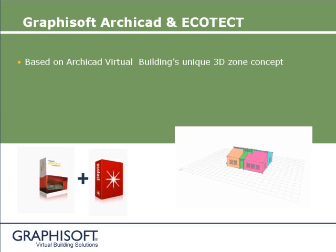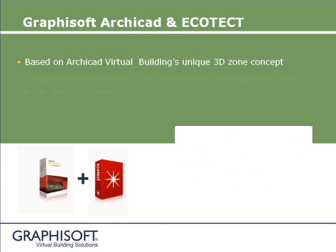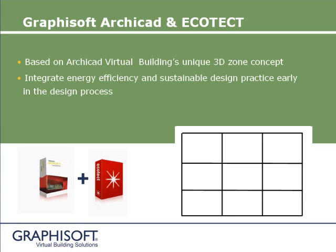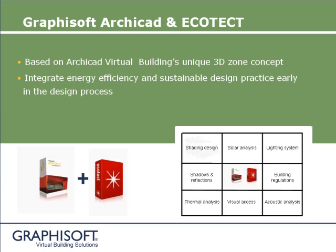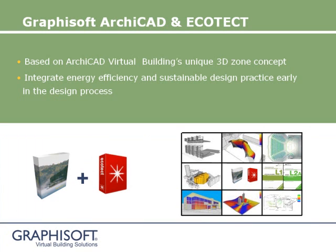ArchiCAD zones, 3D volumes, are the cornerstone of analysis. Together with Ecotect, you can run a comprehensive set of building performance analyses, covering thermal, ventilation, light, acoustics, and more. Designers can get a wealth of information as soon as their ideas are formed into a rough mass model: shade, right to light, building orientation, wind and ventilation, and more. You can use building performance analysis results as part of your design considerations and get a comprehensive design that is environmentally conscious right from the start. It can also be useful at client presentations.